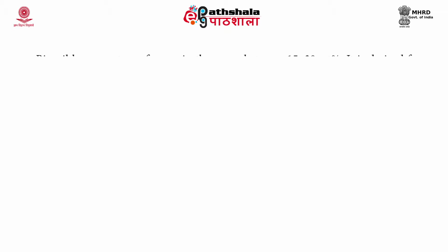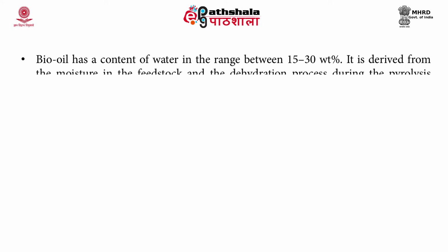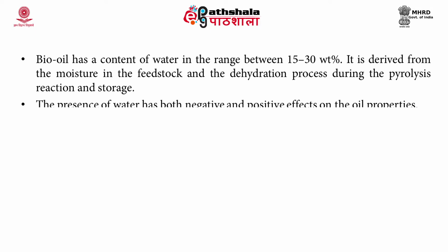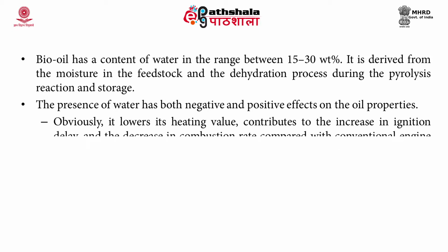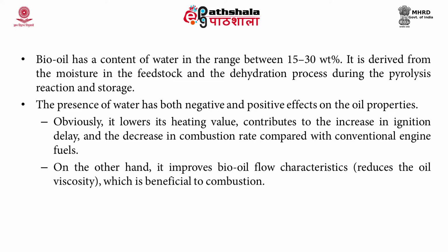Bio oil has a water content in the range of 15 to 30%. It is derived from moisture in the feedstock and the dehydration process during the pyrolysis reaction and storage. The presence of water has both negative and positive effects on the oil properties. It lowers the heating value, and contributes to an increase in ignition delay and a decrease in combustion rate compared with other engine fuels. But it also improves bio-oil flow characteristics and reduces the oil viscosity, which is beneficial to the combustion process.